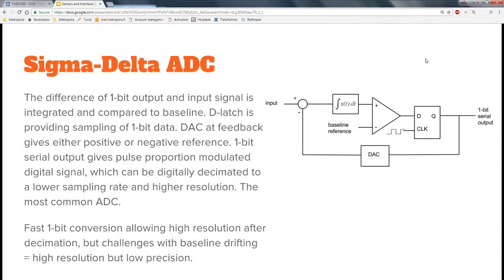And there, sometimes nature is working against you, but sometimes it actually works for you. Another thing about sigma delta is that for higher frequencies, because of the decimation, you start to cut the frequencies. So very high frequencies you cannot detect with this one at all.